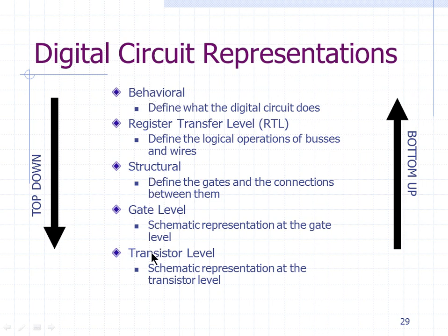Transistor level is not done in Verilog, that's done in CMOS, which is analog design. Digital logic design can be represented in structural or behavioral format. It's called top down or bottom up. Normally, when you design very big chips, you will end up using both behavioral and structural methods for design.